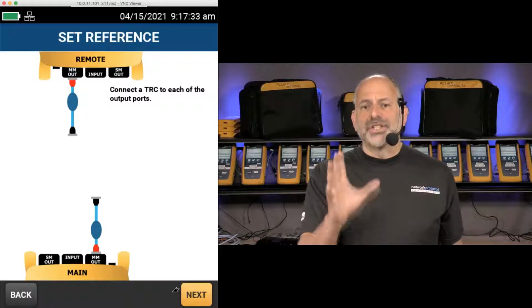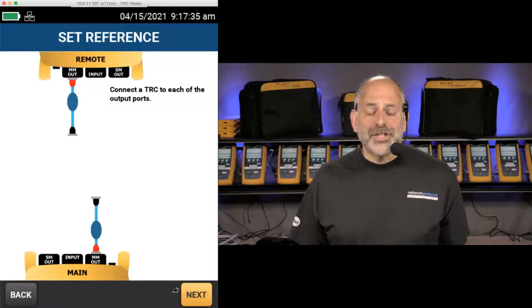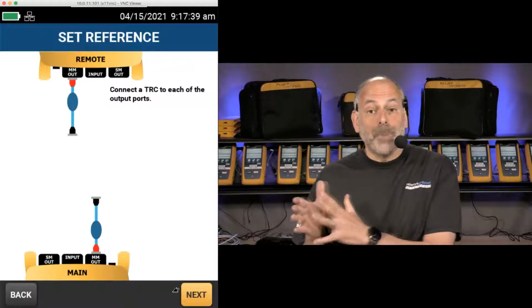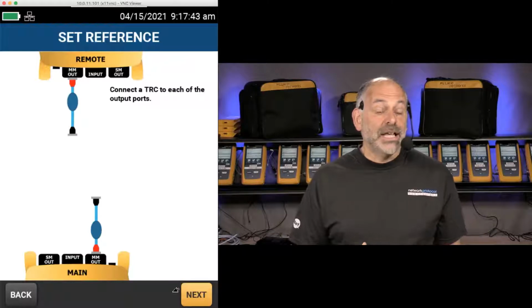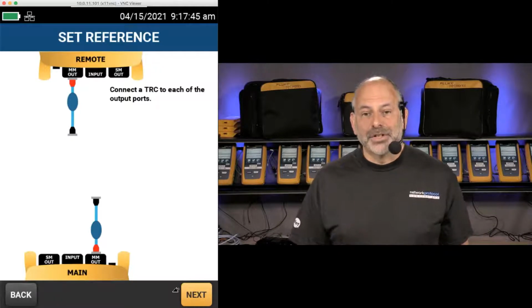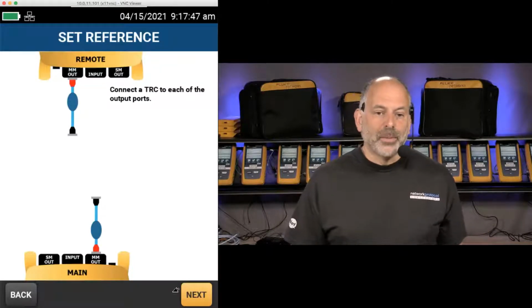And if you notice, as you're going through and doing testing, you start getting negative test results. We expect to see a positive loss. If you get a negative test result, that can be an indicator that you did not give the CertiFiber Pro long enough to warm up.